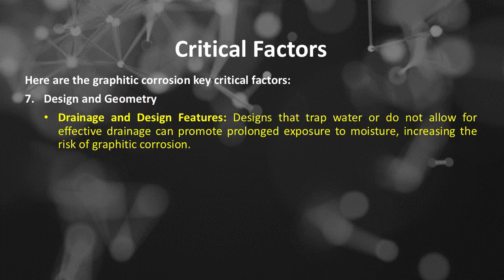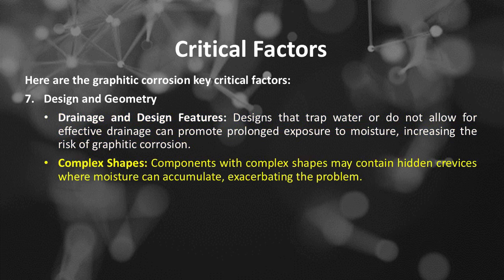Drainage and design features. Designs that trap water or do not allow for effective drainage can promote prolonged exposure to moisture, increasing the risk of graphitic corrosion. Complex shapes. Components with complex shapes may contain hidden crevices where moisture can accumulate, exacerbating the problem.